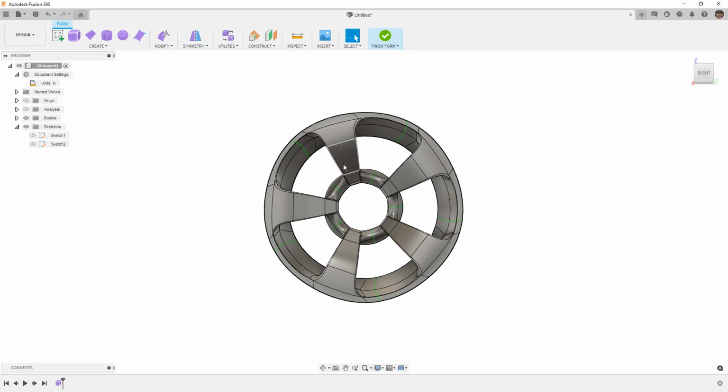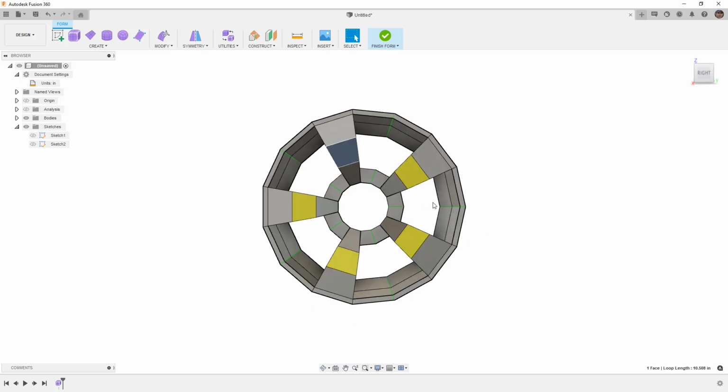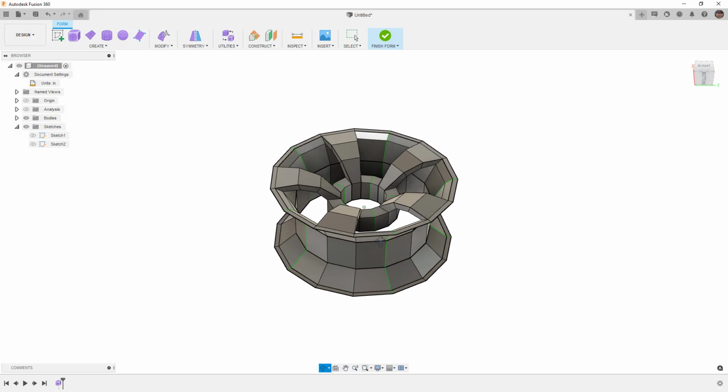And I always do say, make sure that you're comfortable working in box display mode. Box display mode is really going to be the best avenue going forward at really understanding clean geometry, clean patches and clean faces. I know I call them patches all the time. They're just faces, but in this case, it's a good way for you to progress in your modeling and understand the symmetry between all the underlying geometry.